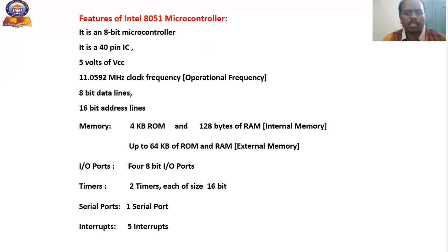And IO ports, one more peripheral. It has 4 8-bit IO ports. Timers, it has 2 timers. Each timer is 16-bit in size. Serial port, it has 1 serial port to perform serial data transfer. And interrupts, it has 5 interrupts.